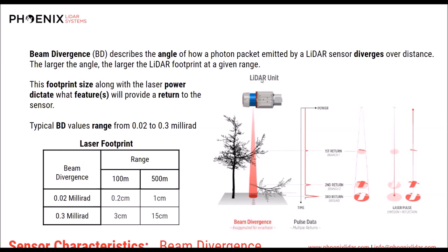So they're going to enable your collected point cloud to be assessed to the geospatial accuracy and reported that way. And that is why you want to collect many ground control points, so you don't have a statistically skewed accuracy assessment.